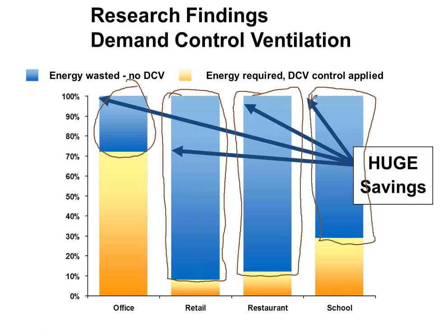Just for starters. And the other thing is every single room in the school has to be designed for the peak ventilation rate, for the peak occupancy of people. But all the kids can't be in every single room to max occupancy at all times. When my kid leaves the classroom and she goes to the gymnasium, there's nobody in the classroom anymore, right? And when she goes from the gym back to the classroom, the gym could be empty. And then outside for recess, and then to the lunchroom, and then to the classroom, and then to the art room. They're moving all over the building. Every room is designed for the peak, but each person can only be in one spot at one time.